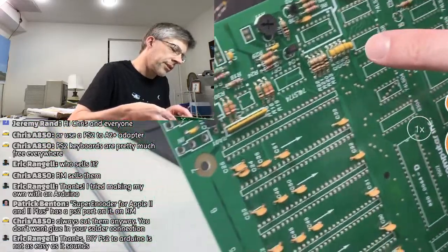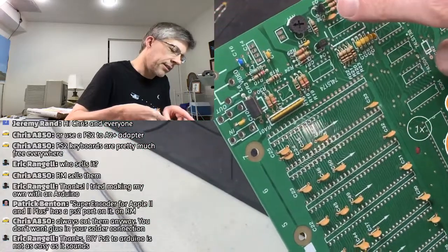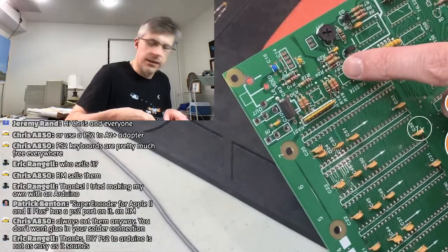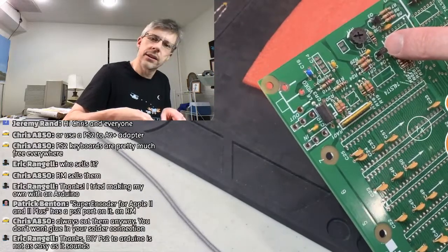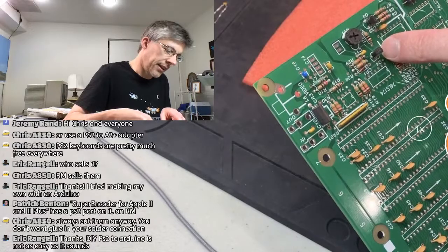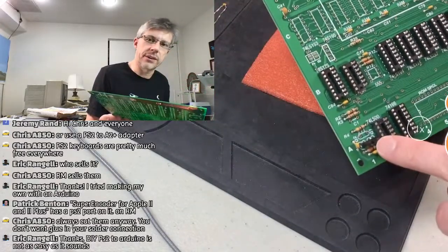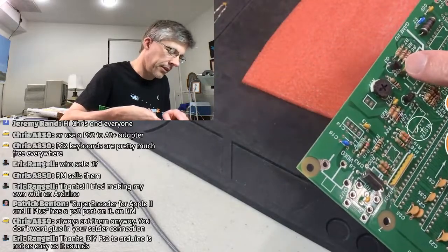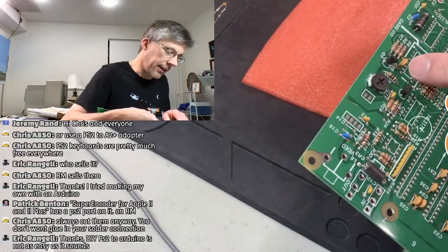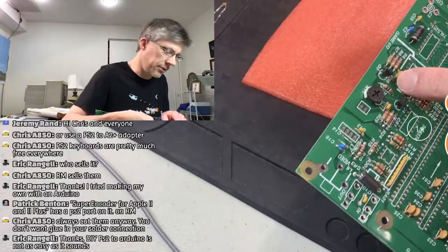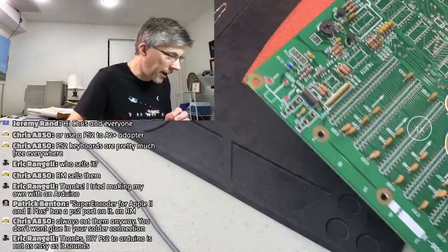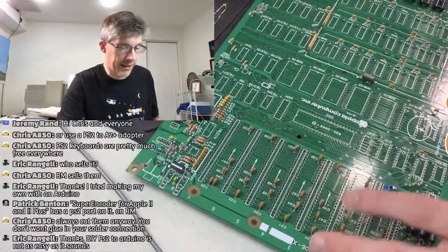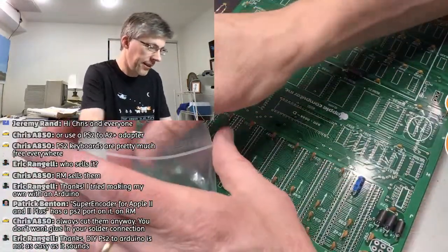And when I was soldering last night, I actually soldered these 2 capacitors here in backwards, because I just wasn't thinking. It was only once I got to the ones down here on the bottom that I suddenly realized, oh, I did it backwards. And so I had to desolder them and put them in again. Luckily, it wasn't too hard to do, but if you can keep it in mind and not do that the first time, that will save you a lot of pain later on. So just be aware of that.